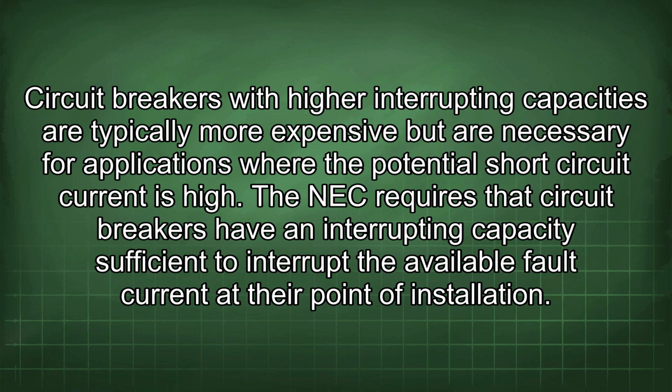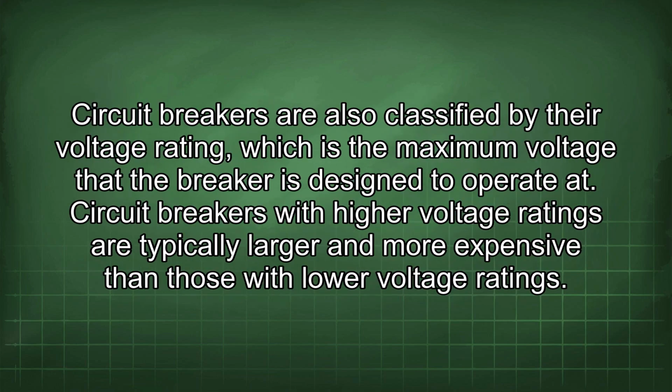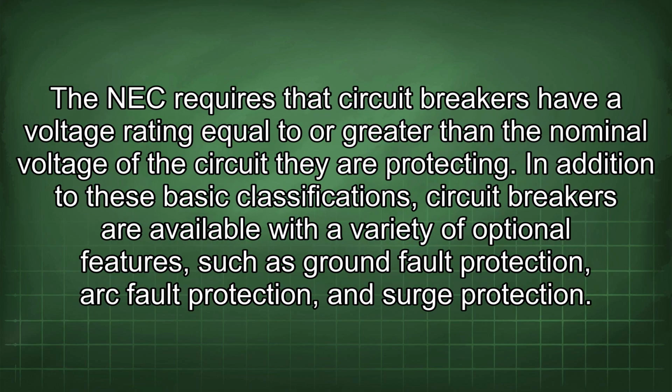their point of installation. Circuit breakers are also classified by their voltage rating, which is the maximum voltage that the breaker is designed to operate at. Circuit breakers with higher voltage ratings are typically larger and more expensive than those with lower voltage ratings. The NEC requires that circuit breakers have a voltage rating equal to or greater than the nominal voltage of the circuit they are protecting. In addition to these basic classifications, circuit breakers are available with a variety of optional features